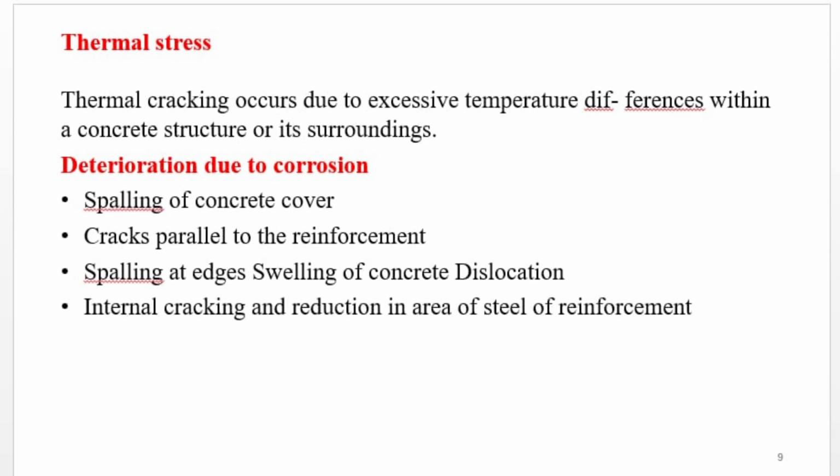Cracks due to corrosion. Corrosion may also lead to spalling of concrete cover, cracks parallel to the reinforcement, spalling at edges, swelling of concrete, dislocation and internal cracking, and reduction in area of steel reinforcement.